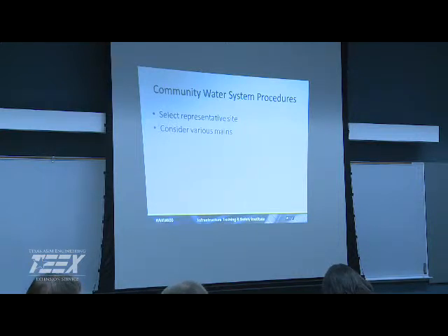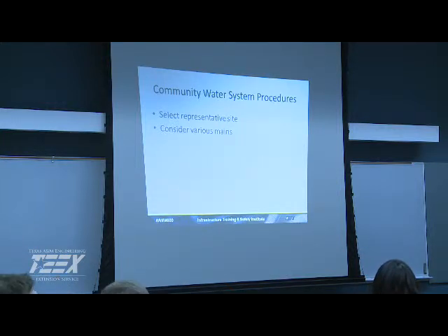Knowing your distribution system. How many have maps of your distribution system? Anybody using GPS to designate your main locations, your valve locations, hydrant locations? A lot of them are getting more and more into that. It's not expensive to get a handheld GPS device and go out and identify where your valves are. Put it on a little spreadsheet, so that if you do have an issue, you can go back and look at your different pressure zones.